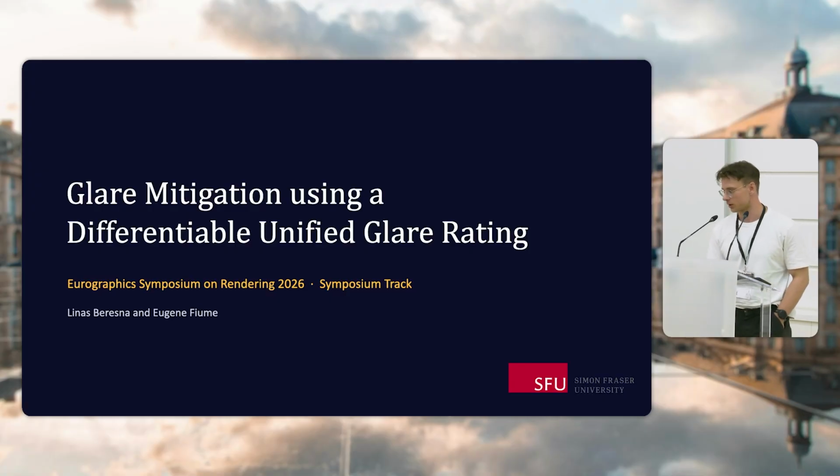I'll be presenting our work on glare mitigation using a differentiable unified glare rating. The one-line version is that we take a perceptual lighting comfort metric, here specifically the unified glare rating, and make it differentiable so it can drive an inverse rendering problem instead of just being a measured quantity.